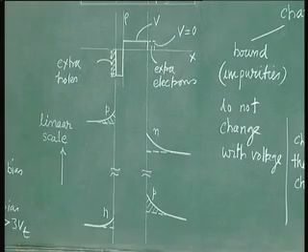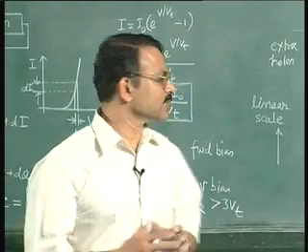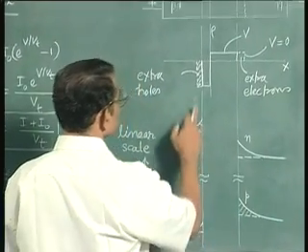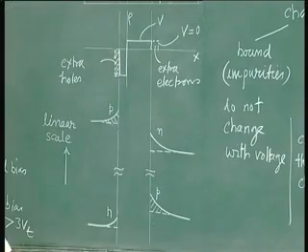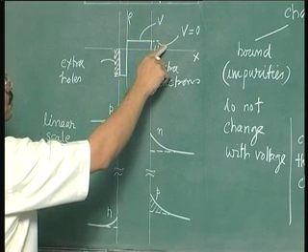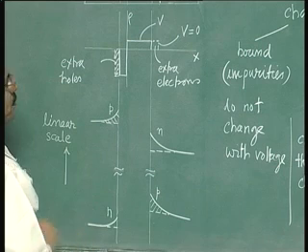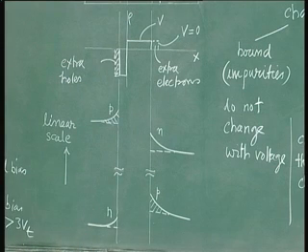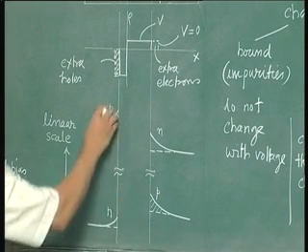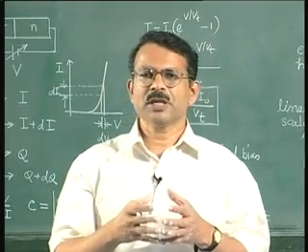So now we can estimate the capacitance by taking the sum of these hole concentrations and then dividing by the incremental voltage. In this case the incremental voltage is V itself, because we are comparing it with respect to equilibrium condition. Alternately, we could write down an expression for these excess holes and we could differentiate this expression with respect to